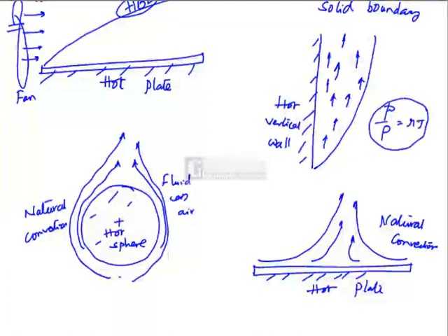As the temperature increases, density of the air will decrease, air becomes lighter, the hot fluid moves up because of the buoyancy forces. The gap or the vacuum left over by this movement is filled with colder and low temperature fluid, which in turn takes the heat and moves up. That is how the convection currents proceed.